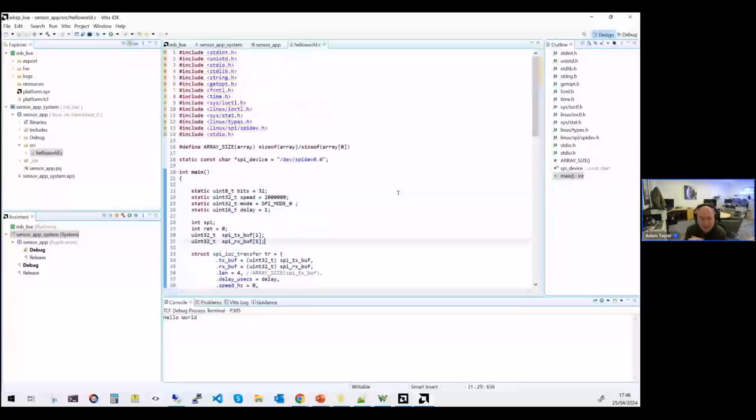And here we can see it gets a lot more complicated now because we're pulling in standard libraries. In this instance, the standard out is going to the TCF connection. If you run it just from the directory where it's been downloaded, over the UART terminal on our Linux machine, it'll pop up hello world over that terminal window as well. So the standard out is the TCF framework and whatever it's been connected to.